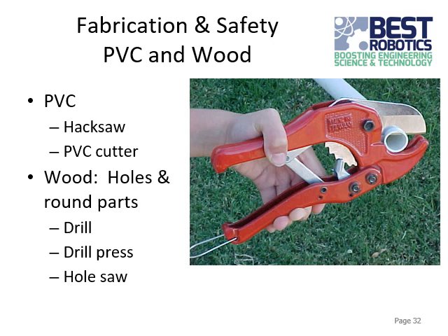Okay, so for PVC pipe, you can, of course, use a hacksaw to cut that. That's what I personally use whenever I need to cut PVC. And that can do a pretty good job of getting you a nice clean cut on the PVC.